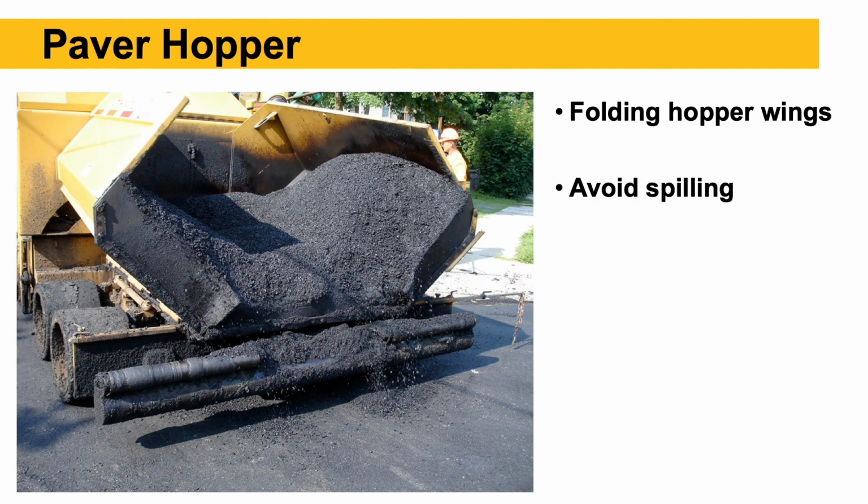Little bit of spillage starting there. Again, that's what we want to try and avoid. So at that point, that's when the paver operator is going to start lowering the wings again and get ready for that next truck to back into the paver hopper.